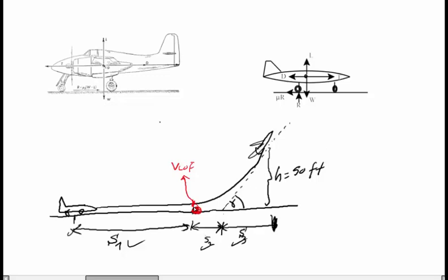Okay, so as I said, from this V lift off to this point, how will we find this point here? We make a tangent line here and cross this line. From the V lift off to this point is S2, and the lift off segment will be S3, from this point to the safe altitude, which is H. Make a straight line here and you find S3.